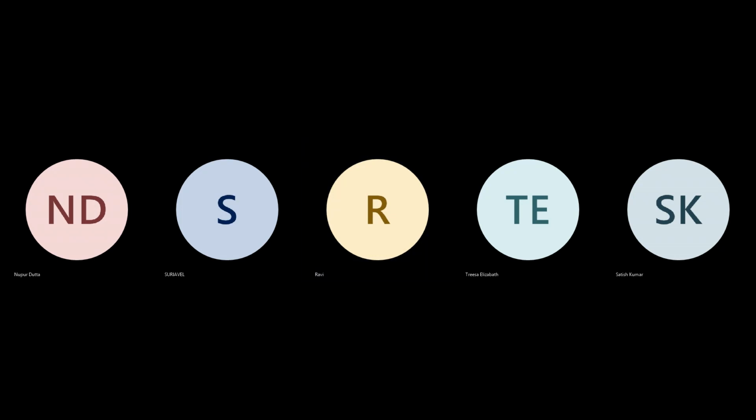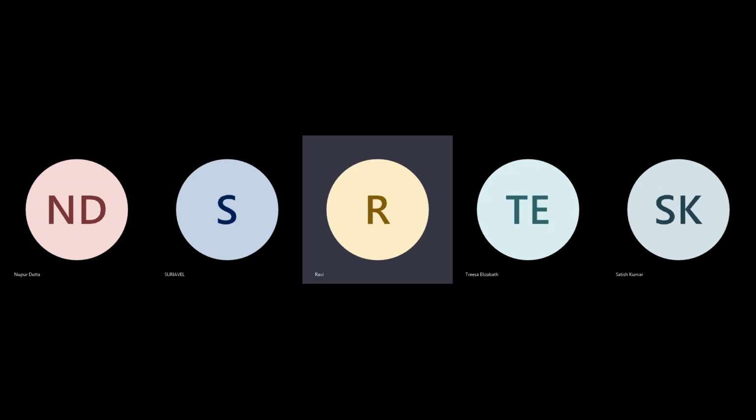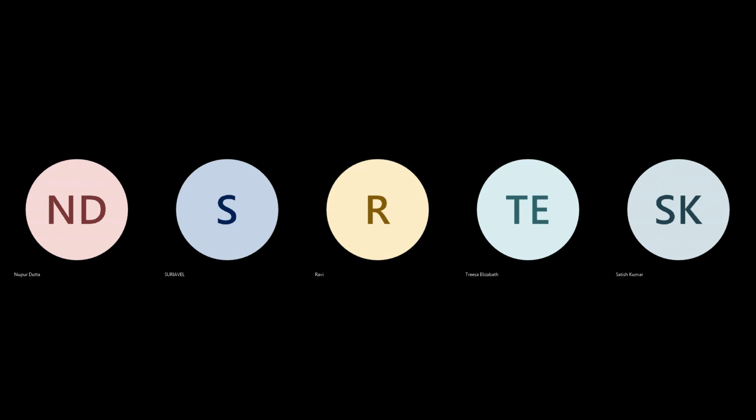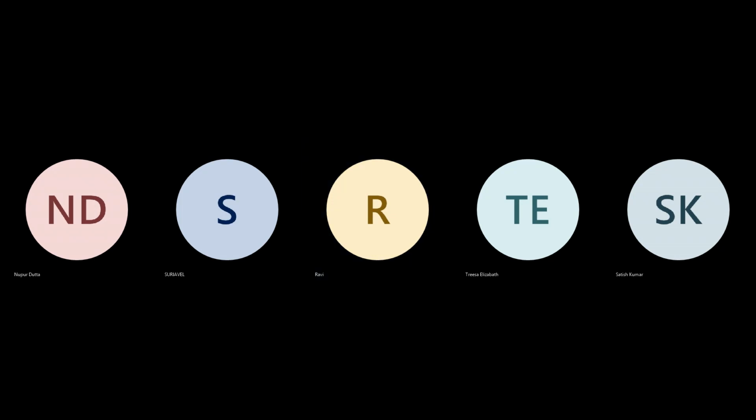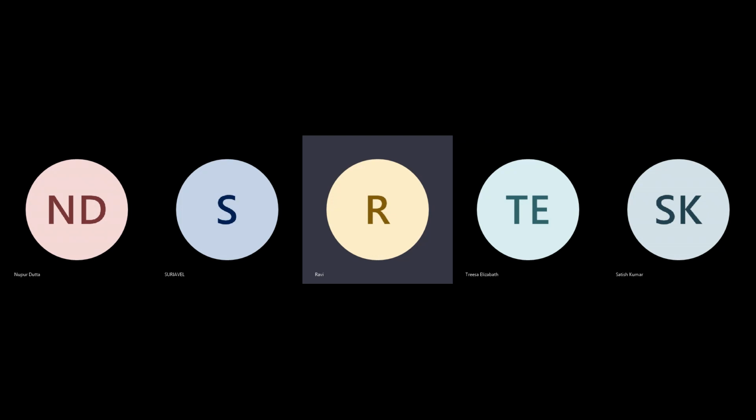You understood? You have to look at placement density. Next, you enable pin density. Let's say your placement density is very low, but your pin density actually has a problem. Then you analyze and see why the pin density is high. If you're seeing a high concentration of complex cells in that area, one of the things you can look at is breaking them down, or use cell padding, which is a later stage.